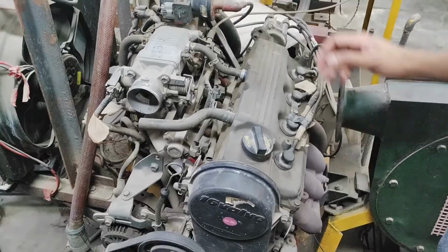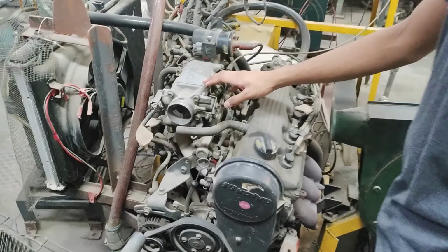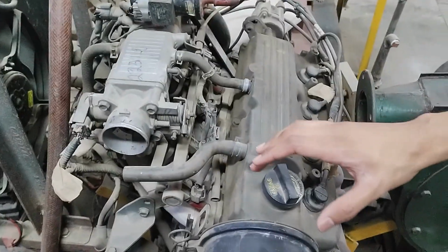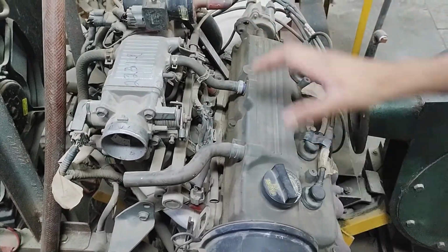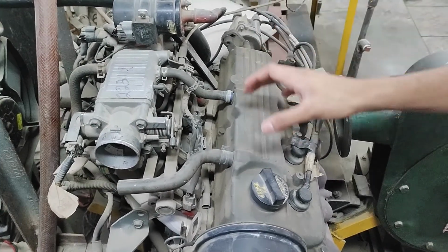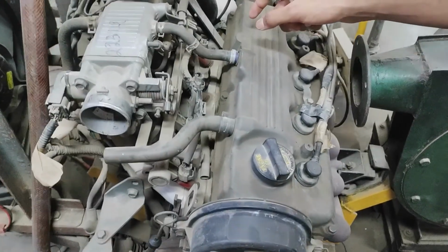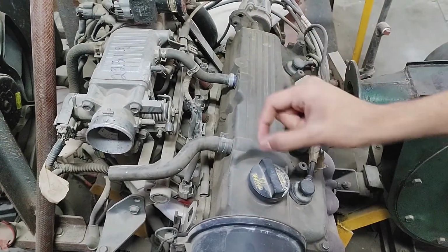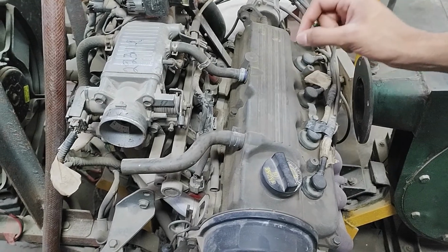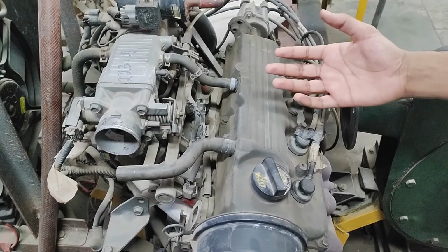these cylinders. A major disadvantage of single point fuel injection systems and carburetors is that the fuel is injected near the throttle body, which means that we can have slightly varying equivalence ratios along each of the 4 cylinders, and this can lead to inconsistent power delivery. So we can overcome this problem with the MPFI system since we are individually injecting fuel into each of the cylinders, and therefore we can have the exact same equivalence ratio, which can ensure complete combustion of the fuel and also leads to lower emissions as a result.